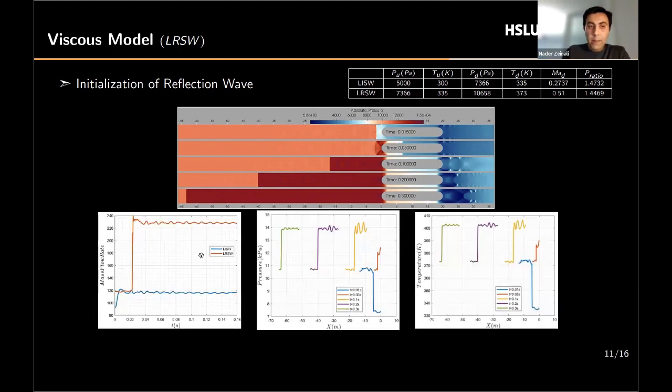So what I explained about the mass flow rates and the new choke condition, actually in the first plot you see that mass flow rate was choked at this value for the incident wave, but when the reflected wave hit the pod at 0.02 second, mass flow rate suddenly jumps in the minimum area and chokes at a higher value. This higher value will result in higher pressure and higher temperature. As you can see, the shock wave being generated is much stronger than the previous shock waves.